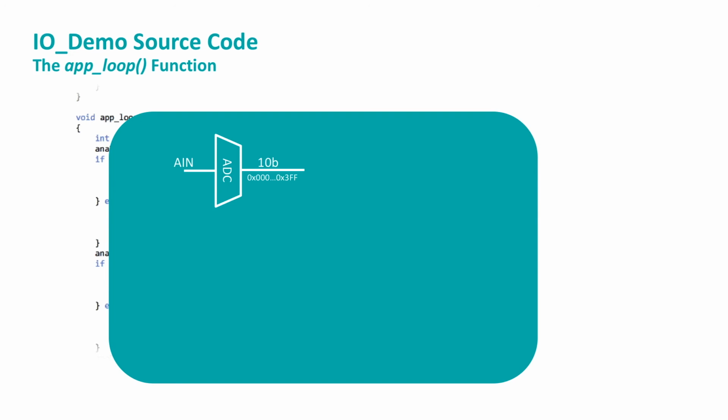The Embed system normalizes those inputs by shifting the value left by 6 bits. So, instead of returning a 16-bit value that ranges from 0 to hex 3FF, the readU16 method returns a 16-bit value that ranges from 0 to hex FFC0, unless, that is, the hardware detects an overflow condition.